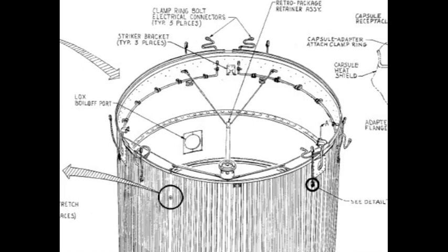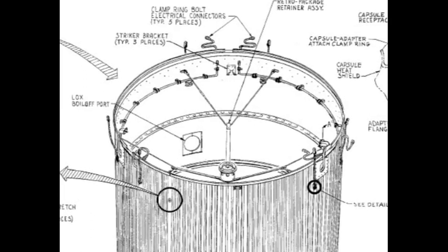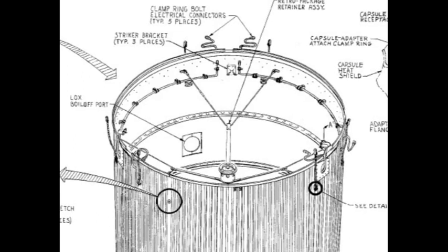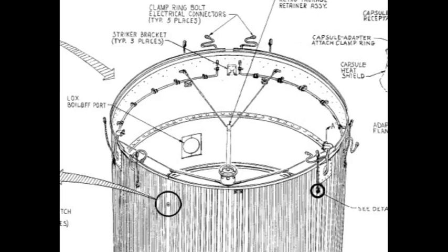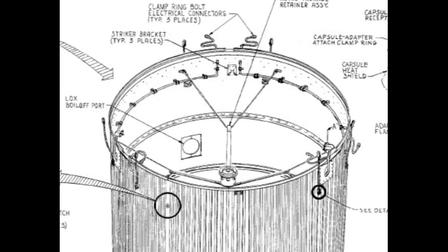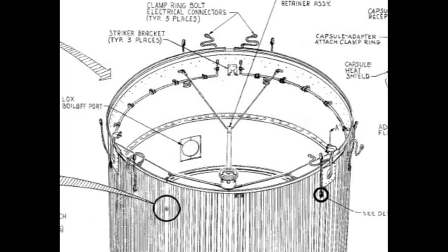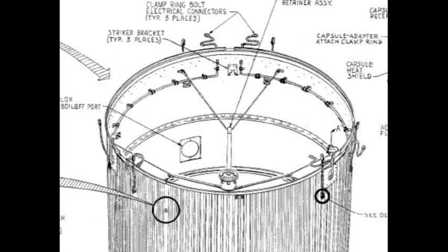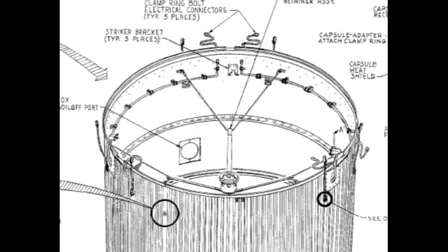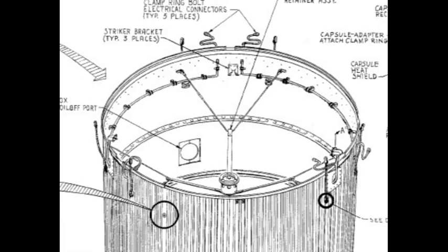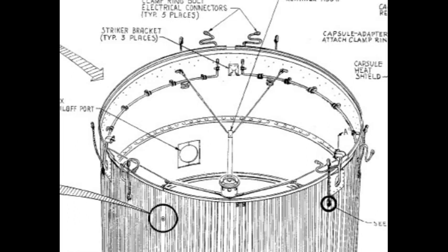A vent port, located in the adapter skin, receives the missile boil-off valve tube and enables the relieving of liquid oxygen from the missile. A fiberglass shield, attached above the vent port opening, streamlines the adapter and shields the boil-off tube. 2 stretch fittings, located 180 degrees apart at the upper section of the adapter, provide a means of supporting, stretching, the missile while in the vertical position following adapter installation.